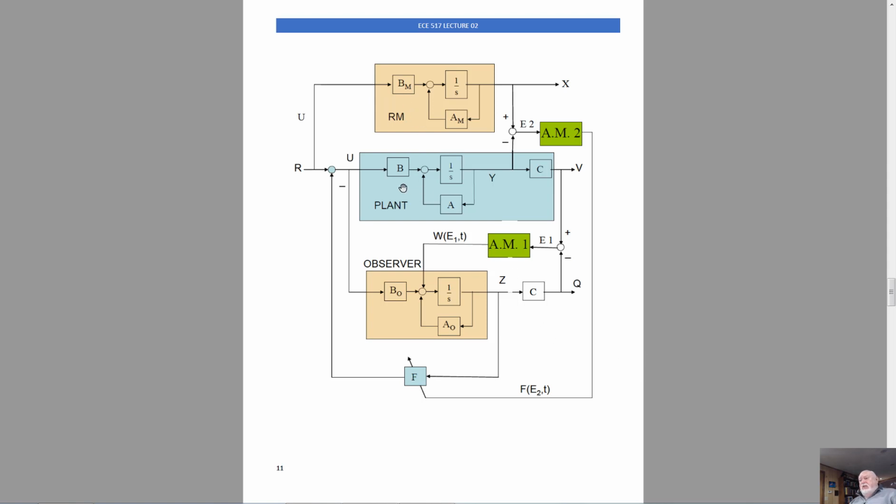If you would know parameters of the controller well, if we wouldn't have the problem of incomplete information, you know how to design a state observer. We would have a great state observer and the system would work perfectly. However, properties of the controlled plant are not completely known. It's a controlled plant with incomplete information, and because of this, Z will never provide a successful estimate of the state vector, unless we introduce a special adaptation mechanism.